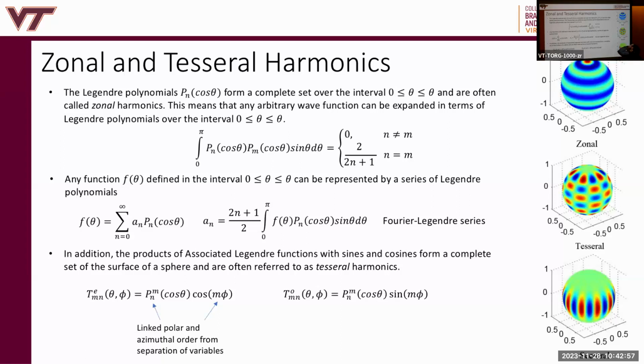So we have, in the radial direction, spherical Bessel and spherical Hankel functions, which are the lowercase j, y, h. They're related to the capital H, Y, and J through some kind of coefficient, like the square root of 2j over pi beta rho, something like that. You'll see in the last lecture. I'll probably remind you in a few slides.